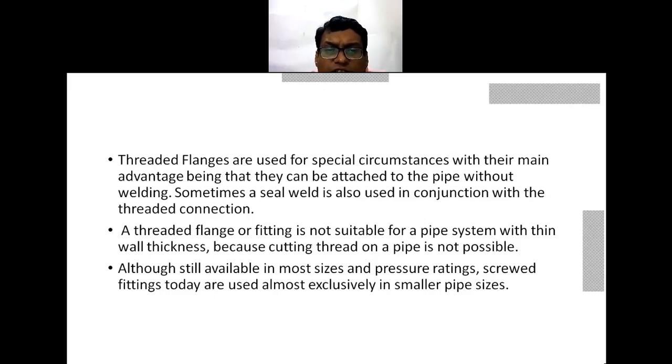The threaded flanges or fittings are not suitable for pipe systems with thin wall thicknesses. That is one of the limitations, because cutting threads on the pipe will not be possible if the pipe thickness is less.